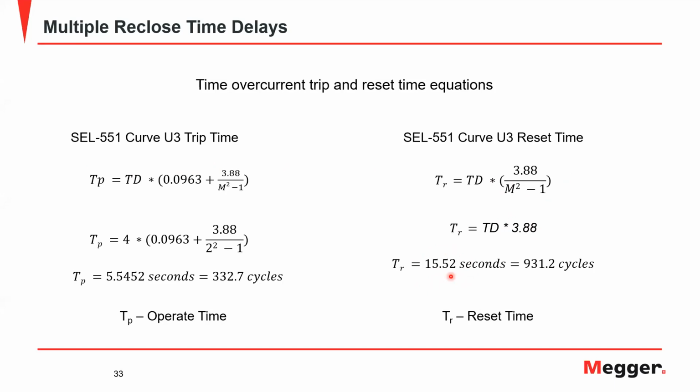The reset time is very slow, and if you've ever seen an induction disk relay work, you'll understand that you can reach up and use your finger or the eraser on a pencil and reset it faster than you can wait on it to do it yourself.